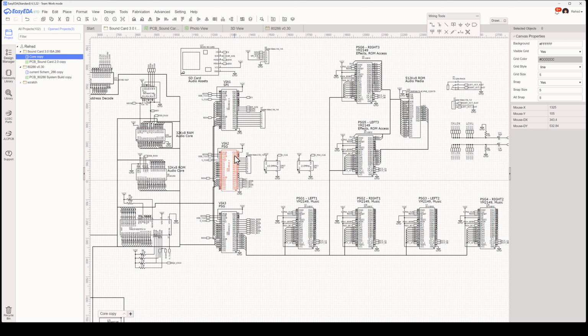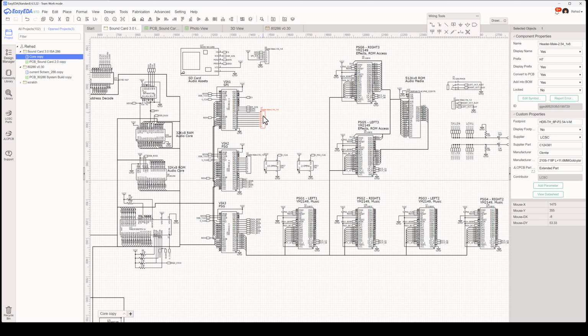And then I have one port on this VIA that's unused, and I'm just going to take it out to a header. And then I have another VIA whose only purpose is to manage SPI, and it is managing SPI to this SD card at the moment, and it has a free header. And I did very seriously consider consolidating these two down. If I have a free port here and a free port here, I could just move this down and have one fewer IC, one less on my design. But I wanted to have at least one port that was open for debug purposes.